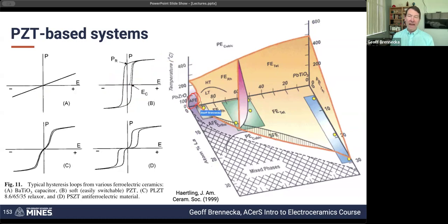You'll notice down here the antiferroelectric orthorhombic phase of lead zirconate. If we play around in that region, we can help to stabilize that by adding lanthanum, and now we have this region of antiferroelectric response that adds possibilities. We can have a very slim loop antiferroelectric, or we can have one with a little bit more width to it, depending on what application we want.